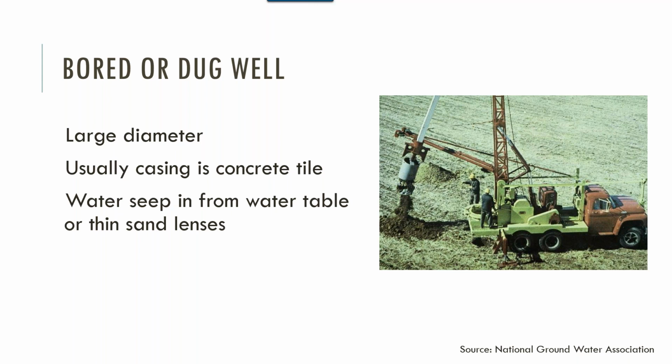So usually you put a dug and bored well in, a large diameter well, when you don't have an aquifer that's either there's not enough quantity of water or the water quality is poor. We have areas all around the country where there may be some kind of contaminant, or it may be salt water. I know in southern Illinois, when you get to a certain point, all of the shallow bedrock has a TDS of over 10,000, which is basically salt water, seawater, and so that's not really potable or able to use for drinking water supply.